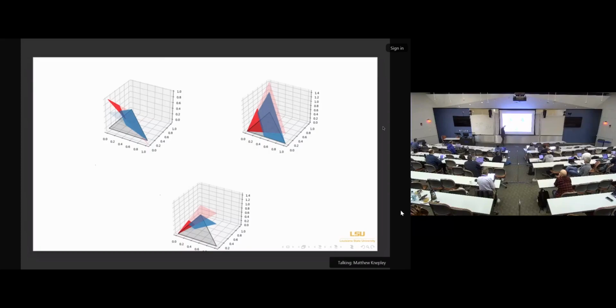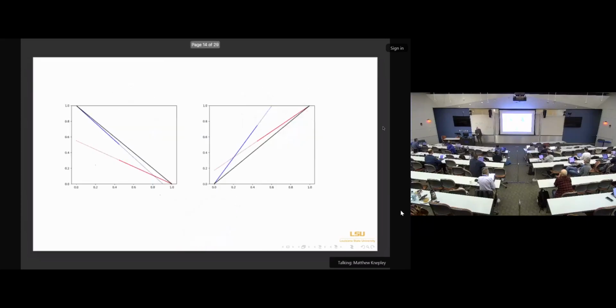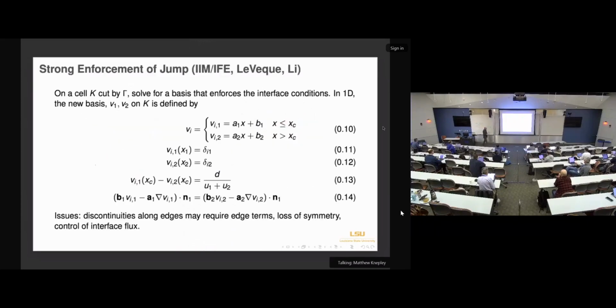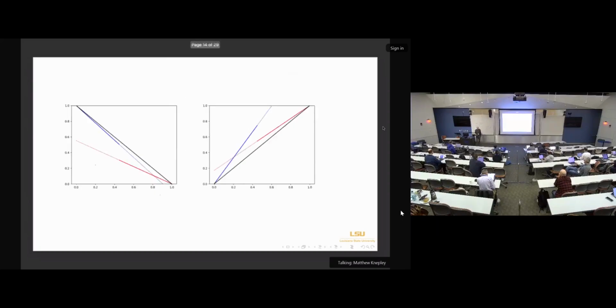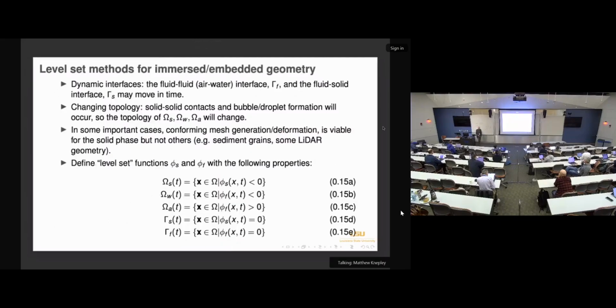So these, again, the new basis functions are the darker parts of these. They behave at the nodes just like the old basis functions, but they have a break in the slope and potentially in the continuity. So that's all I'm going to say about those. The tricky thing about this from an implementation perspective is that you do have to have some way of doing subcell integration because of the break in continuity or the change in slopes. And I'll talk a little bit about how we do that, which is something separate.